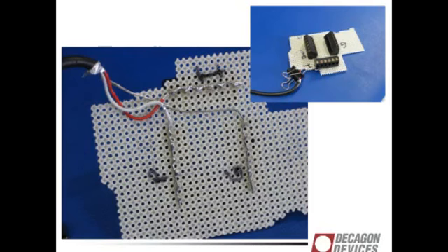Note, I want to point out this part right here where all these wires are crossing. This is fine, but if something moves in this, if this ground wire crosses with this bare part of the red wire, you're going to lose your bus. So even though this bus works pretty well, this is a warning flag right here. I don't want these wires crossed, otherwise it's not going to make me happy.